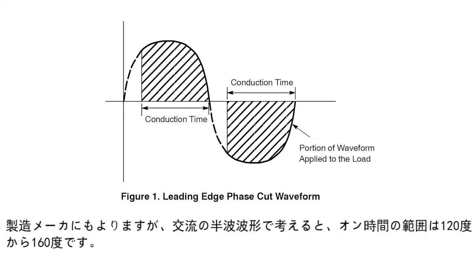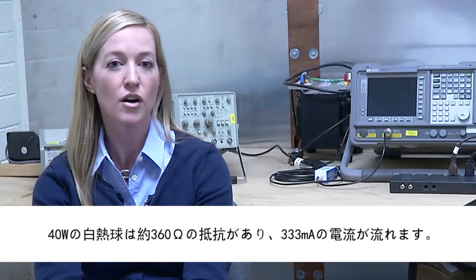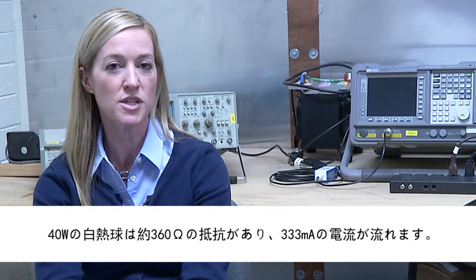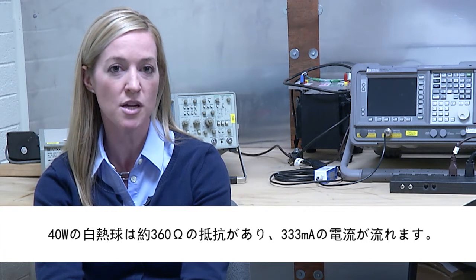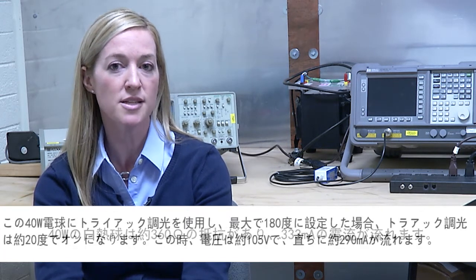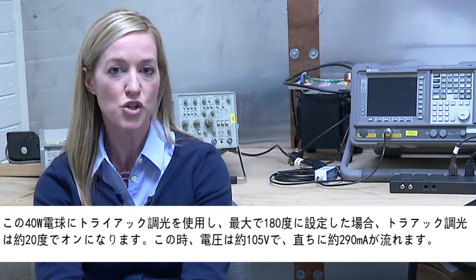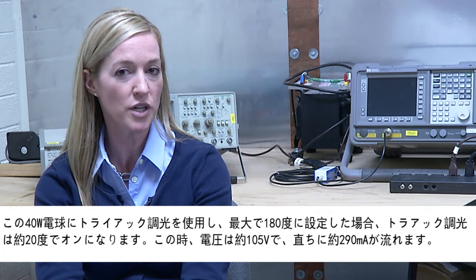The maximum conduction time ranges from 120 degrees to 160 degrees of the 180-degree half-wave AC waveform, depending on the manufacturer. The majority of Triacs used need a minimum of about 40 milliamps to function correctly. A 40-watt incandescent bulb has a resistance of about 360 ohms and draws about 333 milliamps RMS. When using a Triac dimmer for this 40-watt bulb and setting it for maximum 180 degrees, the Triac dimmer will turn on at about 20 degrees.